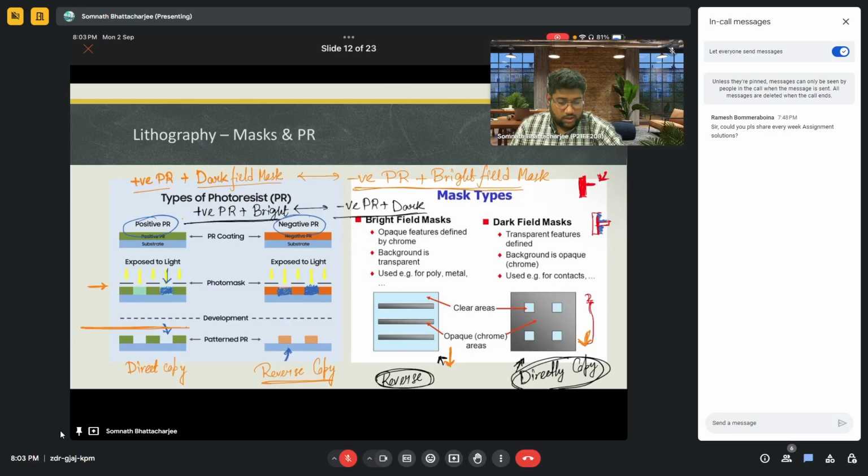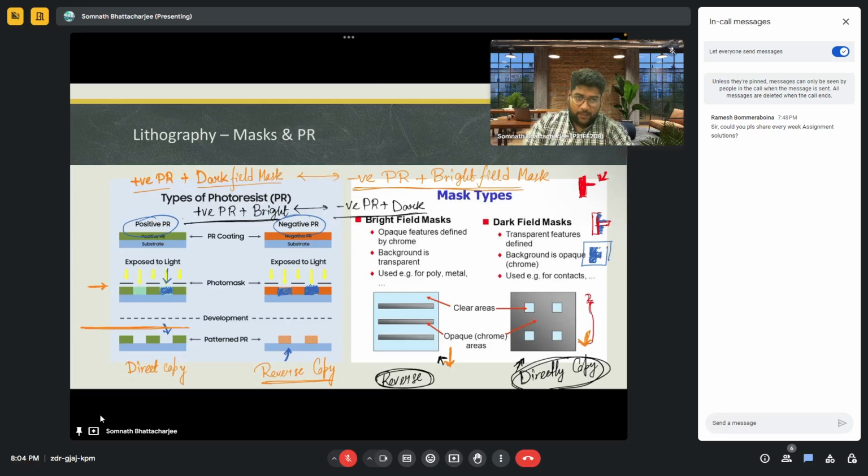But if you are using a totally clear mask with this amount of area, the shape will be very fine. Although there will be another problem: you will have to etch away a very huge portion. It has to be a very perfect etching where you need to etch the exact amount, and you don't need to over etch or under etch the areas.